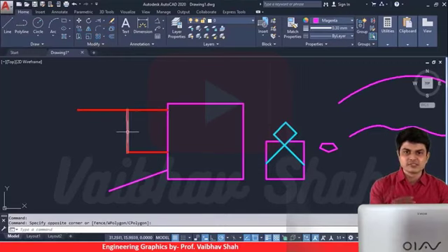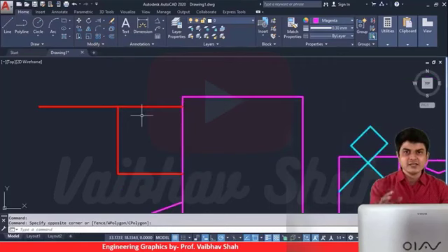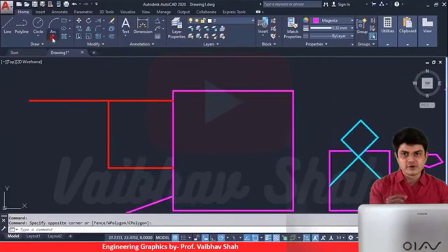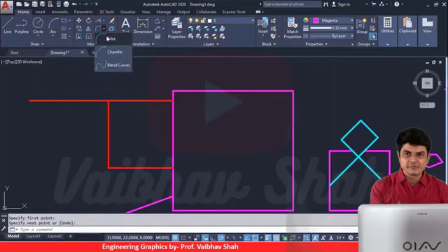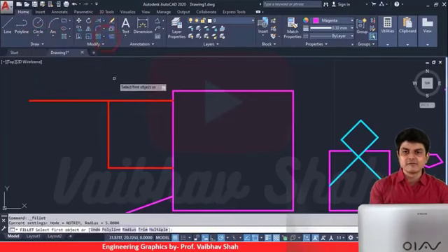So you need to just first make the fillet in the intersection of this horizontal and vertical line. So how to make the fillet? For that you can use an arc, or you can even use a circle, but it will take a lot of time because you need to use a trim. So we will be using the fillet command directly. It will give you the result directly.